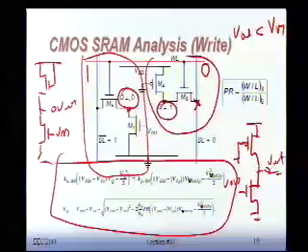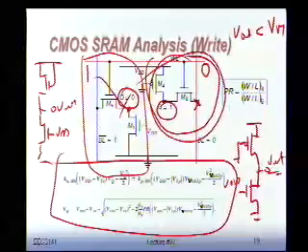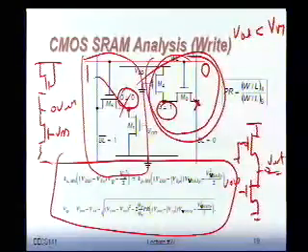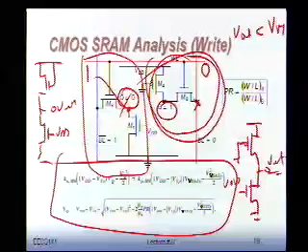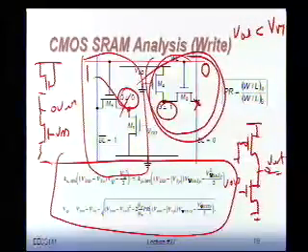Why? Well, it's feedback, right? In this case, actually, this doesn't matter, because if I can make this node flip around, if I can force this thing to 0, at that point in time, the feedback comes into action, and this doesn't matter. It will make the thing move. Okay? So we have to be very careful with those conditions, because they might look bizarre, because, hey, this is one way, the other way, this way. So what's going on here? So with sizing, SRAM is very important. Basically, making sure that the cell is small and that it still works is very crucial.